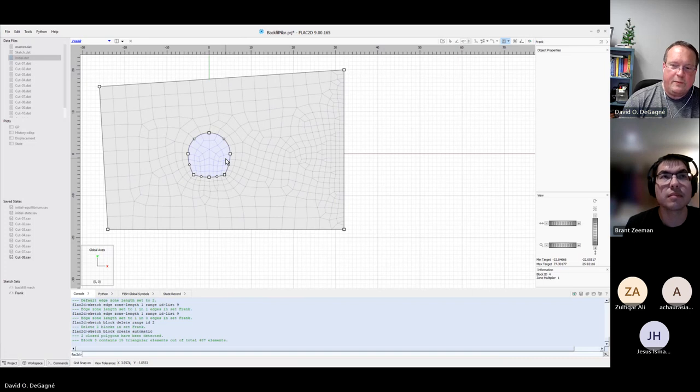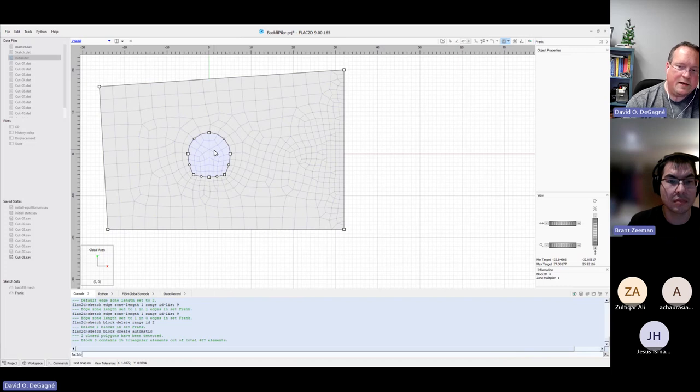But what you often will see is these sort of artificial implosions. And sometimes you want that. Maybe you're studying rock bursts or something like that, and you want to have a high rate of closure. So what we have is a relaxation command that lets us essentially pick a material, some group like tunnel, and then we can essentially gradually over several steps relax it.